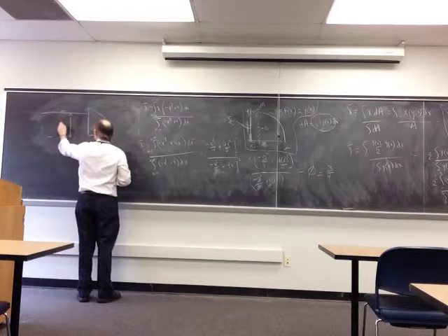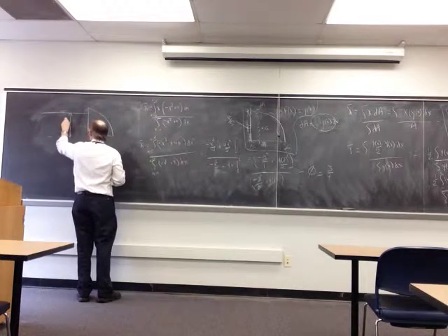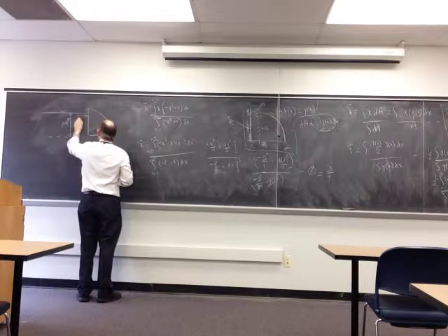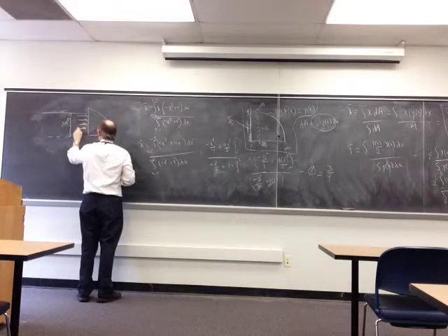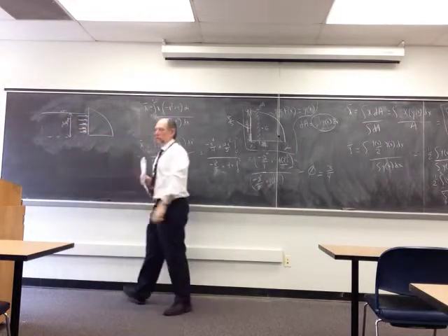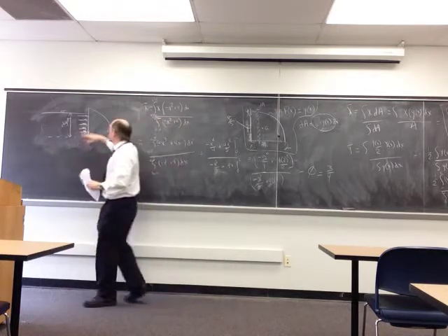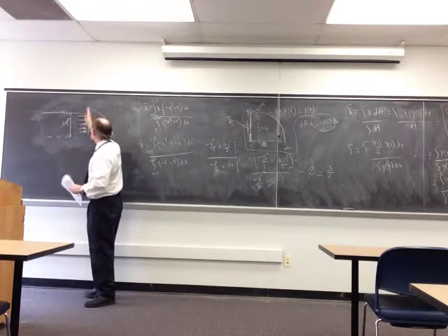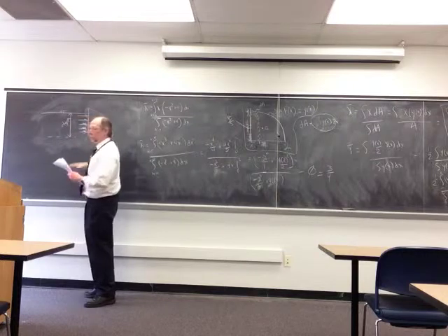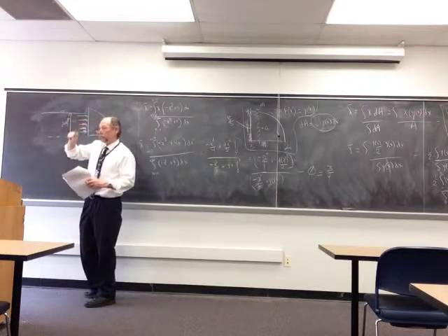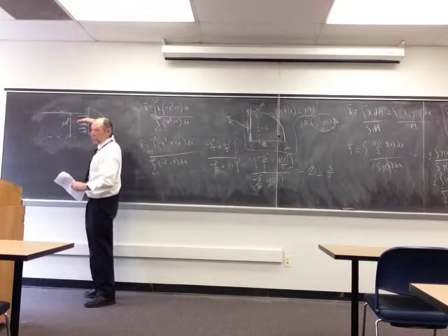You've got hydrostatic forces across this entire face. That hydrostatic force, assuming this is a vertical wall, can be resolved to a single point force at mid-depth.